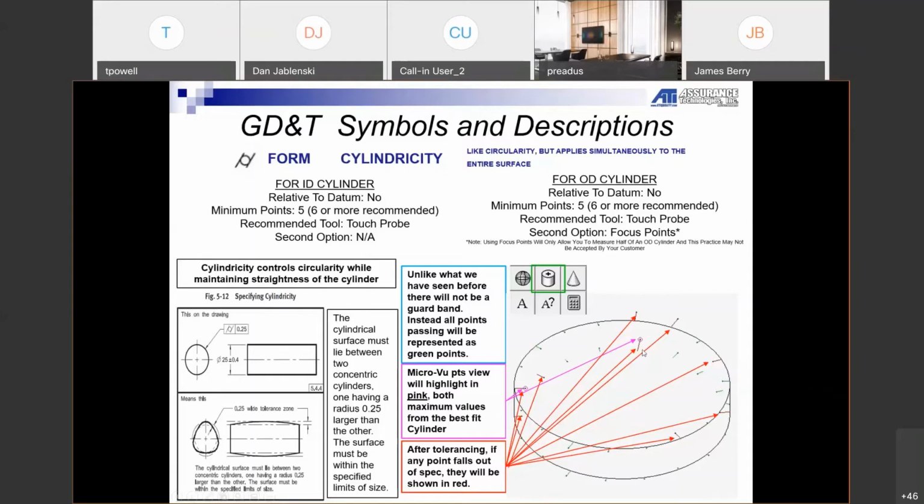Some of the first things to check is, is there a burr in there that the touch probe is hitting off on? Is your touch probe ruby ball not large enough to get inside that? And, kind of do those things before reporting that it's out.